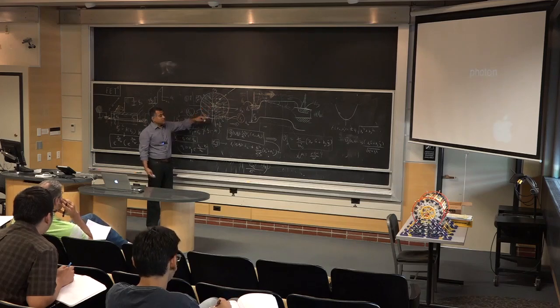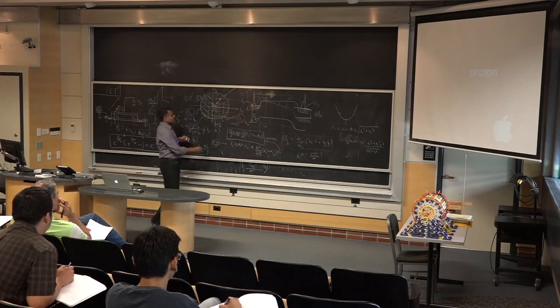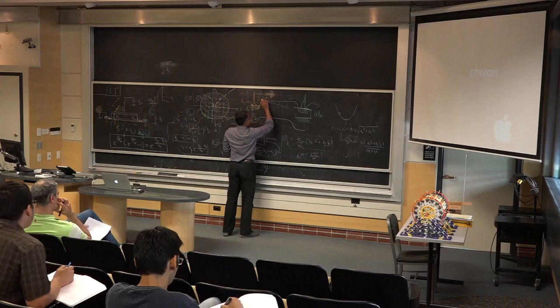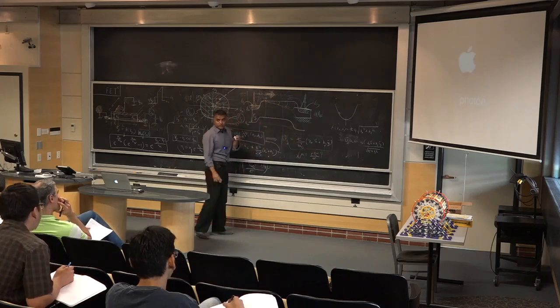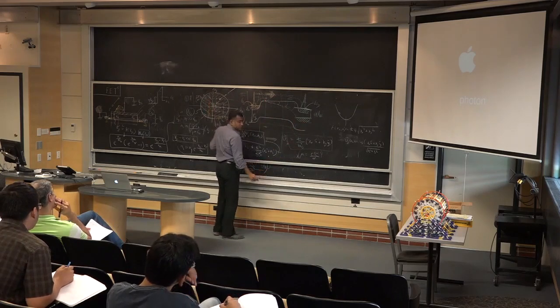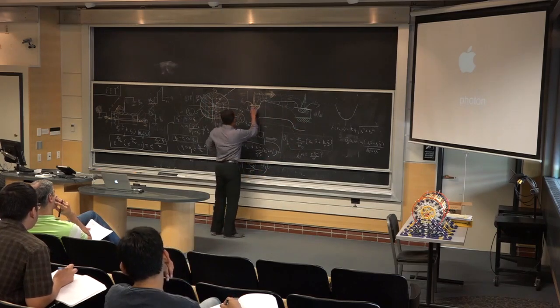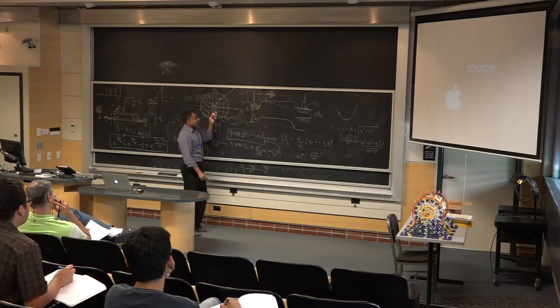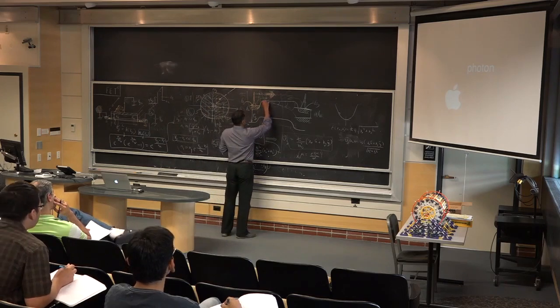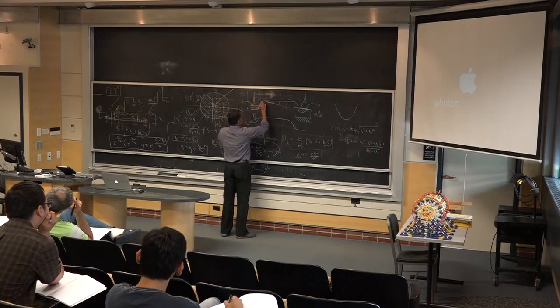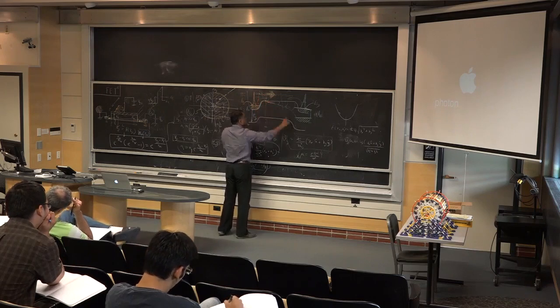So yeah, it'll change, right? It can change, but it depends on where you are in the channel. That's the important point. If you're sitting here, then that's still like that, right? The right-going part is like that. I don't know what the left-going part is now. But there's one point of very great interest, and that point happens to be what's called the source injection point. You see, because the bands bend like this, it goes from a positive slope to a negative slope.